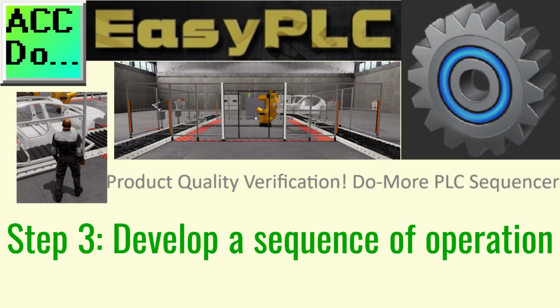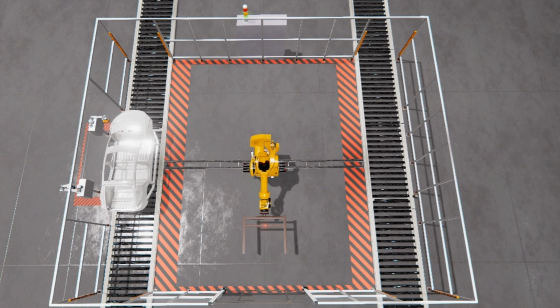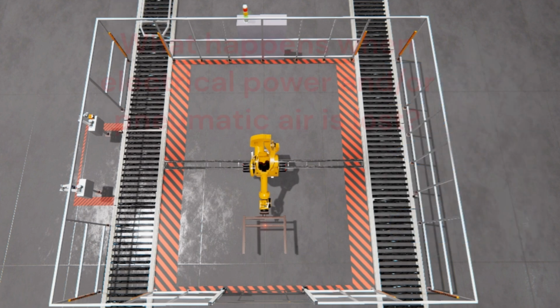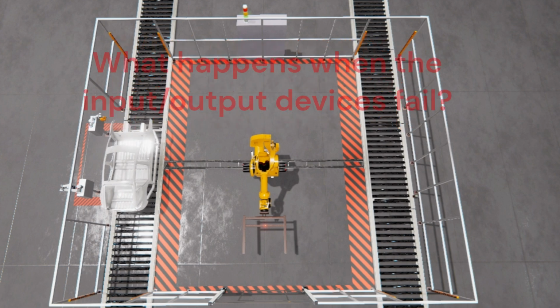Step 3. Develop a logical sequence of operation. A flowchart or sequence table is used to understand the process that must be controlled fully. It must also answer questions like this. What happens when electrical power or pneumatic air is lost? What happens when the inputs and output devices fail?